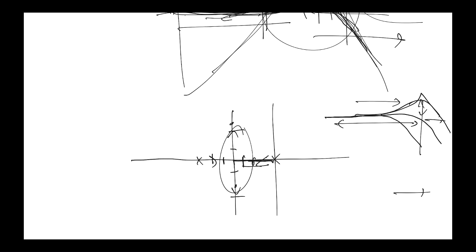So just understand what things mean, understand how to do the analysis, and apply that to the specific situation you're dealing with. There are no generic rules that apply everywhere. The only thing that always applies is what the phase margin means. It's the phase of the open loop transfer function at the crossover frequency. The crossover frequency is where the open loop transfer function has a gain of 1, right? And what remains the same is that there's a relationship between how much peaking you get and the phase margin.